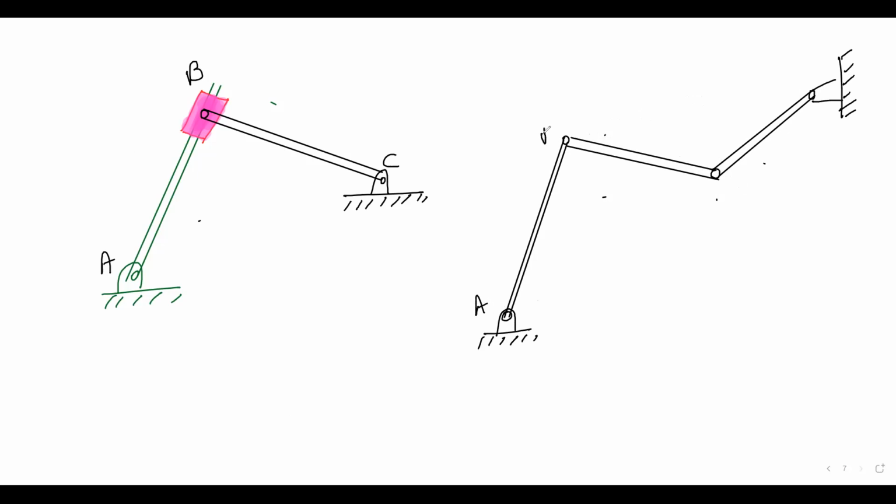A, B, C, D. Clear, right? Now when you're trying to find the velocity of B using A, it's hard, because there is a small xyz term. But velocity of point B using C is easy, because there is no small xyz term: the collar and the distance BC does not change. So you can easily get the velocity of B using C. And then using A, you can crash the small xyz term.